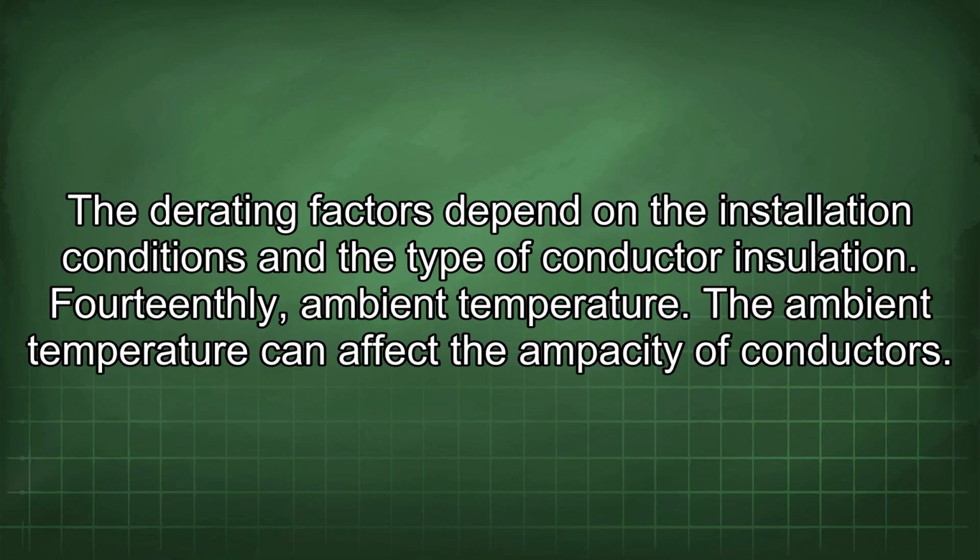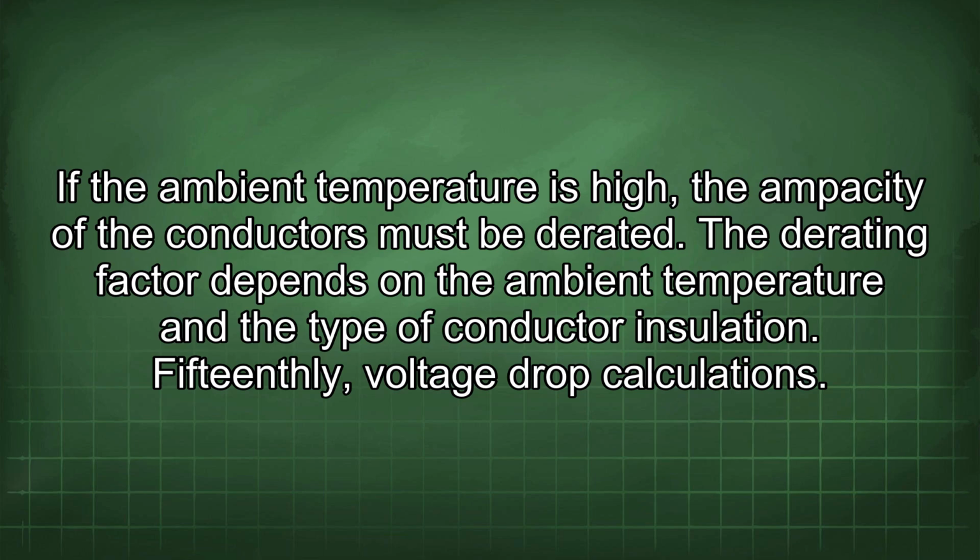14thly, ambient temperature. The ambient temperature can affect the ampacity of conductors. If the ambient temperature is high, the ampacity of the conductors must be derated. The derating factor depends on the ambient temperature and the type of conductor insulation.